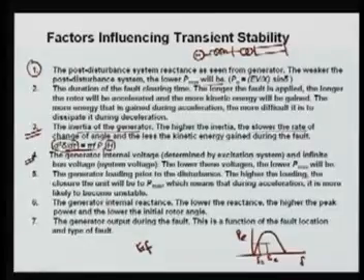At this point E F, the excitation voltage, is at angle delta, and here V infinite is at angle 0. This E F can be changed by changing the excitation of the alternator. In an alternator we have two control loops. One controls your real power, and that is related to your steam.